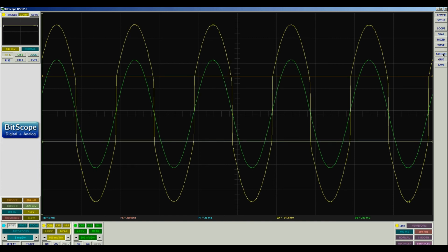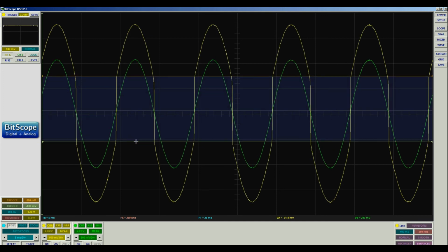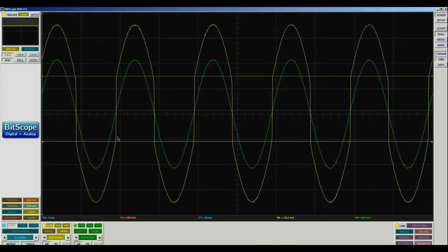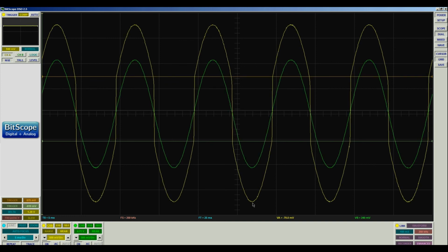We can measure the deadband. The op-amp output jumps through the deadband, and it goes from 610 millivolts to minus 610 to approximately 670. Not quite symmetrical, but still we can see the feedback is now doing something useful. It actually reduces the distortion in the output.